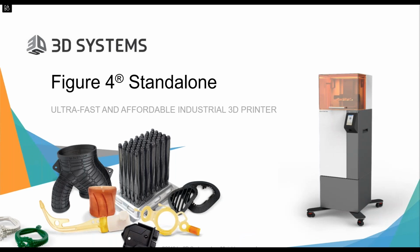The Figure 4 is a DLP technology, which stands for digital light projection, sometimes referred to as micro SLA. But this again is a pool of liquid. The parts are built a layer at a time. This allows you to print a lot of parts very quickly, and it's very affordable from a material cost standpoint. It's perfect for low volume production and same day prototyping. There are many material options on this platform as well. You can easily change out materials for a variety of applications, but on this platform, just remember it's fast and it's inexpensive parts.